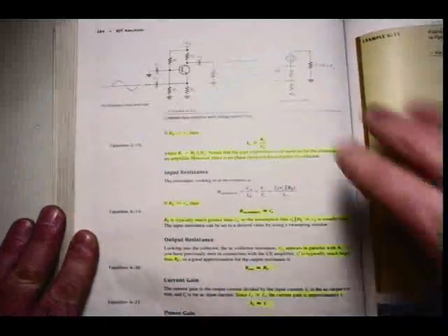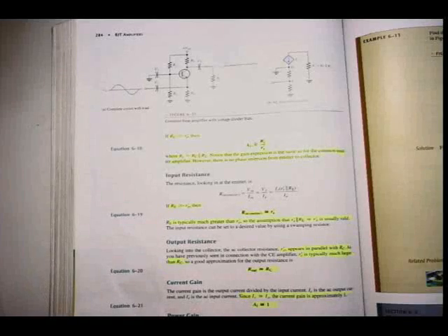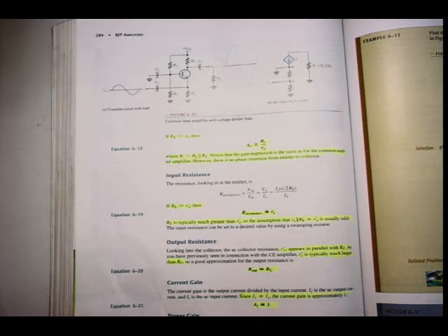We turn the page. We've also seen a rule of thumb. If RE is much smaller than r'e, this simplifies down to voltage gain of rC divided by r'e, where I know of course that lowercase rc is RC, the resistance at the collector, in parallel with the load resistance, RC in parallel with RL. And you will also note again that the gain expression is the same as for the common emitter amplifier that we have discussed previously. However, please underline, there is no phase inversion from the emitter to the collector, because the input is at the emitter and the output is at the collector. There's not going to be a phase inversion.